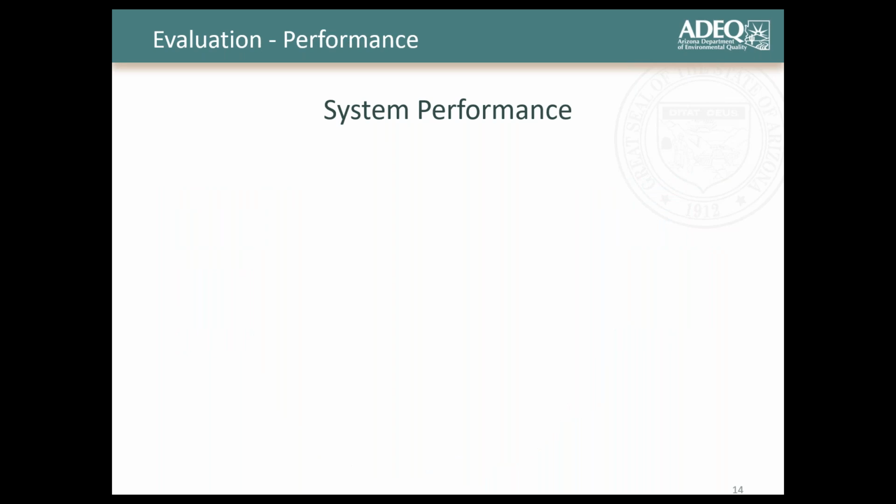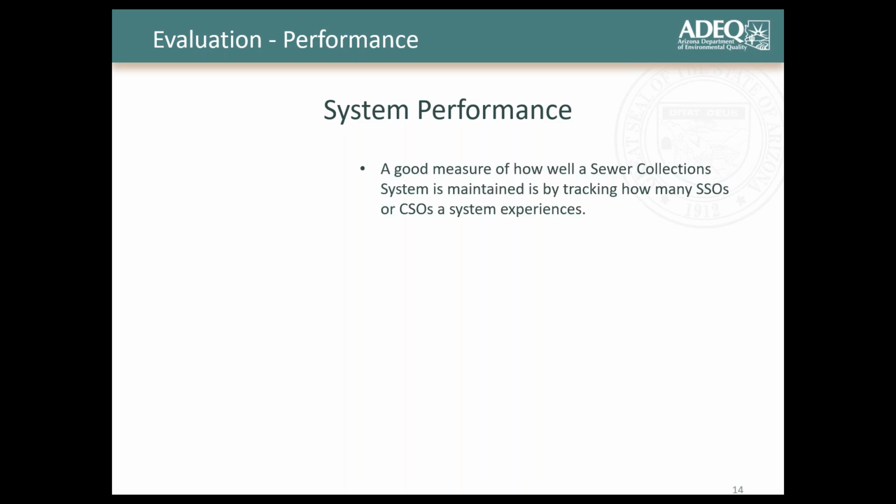So one of the things that you want to evaluate, right, is your system performance. When you're looking at all these CMOM programs and trying to keep these permits up to date, or trying to make sure that you're staying within the regulations, you really want to evaluate how well your system is performing, right? So you want to analyze your overall system performance. A good measure of how well your sewer collection system is maintained is tracking how many SSOs or CSOs your system is experiencing.